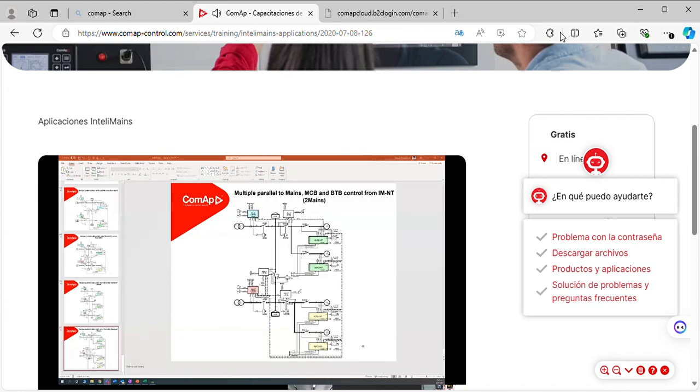And if I return the grid back to normal, if I bring back the grid, so mains return, it will check if the grid is healthy and it is restored. It will automatically synchronize here. So you can see the grid is trying to synchronize. So the grid synchronized, and gradually the load is getting transferred. So there's a breaker overlap we are performing. And once all the load is transferred back to the grid, the MGCB opened up, and now the gensets are going back to standby mode.